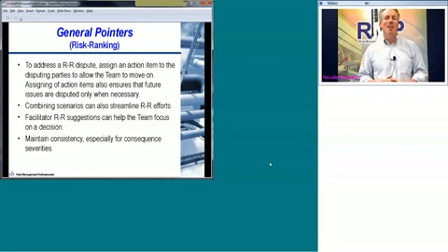Combining scenarios, or especially combining causes, can streamline the risk ranking effort. There's usually no reason to have a cause for a valve mechanically failing open, then another cause for a controller causing the valve to open. These can often be combined, as well as the bypass. Pulling all those together means you think about it once, do a good job at one point, and not be risk ranking all those little details.